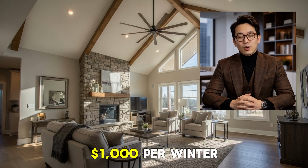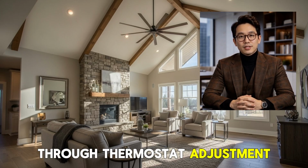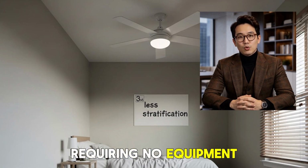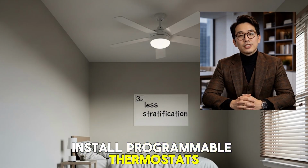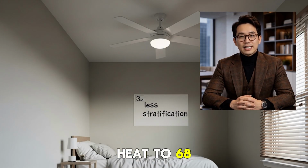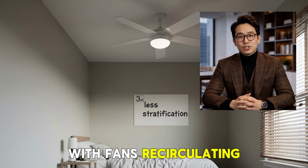A household spending $1,000 per winter on heating reduces that to $700 through thermostat adjustment and fan direction. $300 saved every year from free changes requiring no equipment purchase. Install programmable thermostats to automate temperature reductions during sleep hours and away periods. Heat to 68 degrees during waking hours with fans recirculating air.